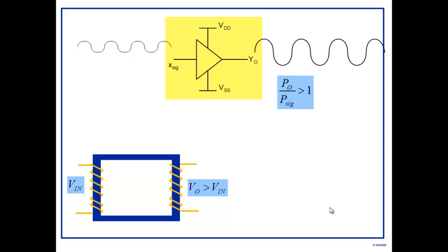When do you call something an amplifier? It's not simply that the ratio of output voltage and input voltage is higher than 1. You can only call something an amplifier if, besides that, you get output power more than input power. Then only you can call it an amplifier. Otherwise, you can't call whatever device it is an amplifier.